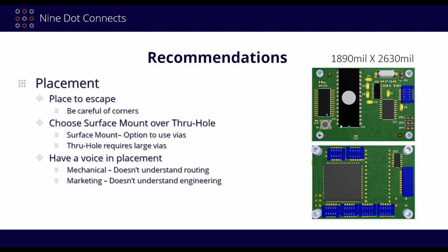this particular EEPROM, each one of these through holes is 60 mils in diameter. So that's taking up a lot of board real estate over here. So that's the other thing to keep in mind too. So if you can keep the surface mount, all the better. If you can't avoid it, that's not a big issue, but that's the recommendation here.